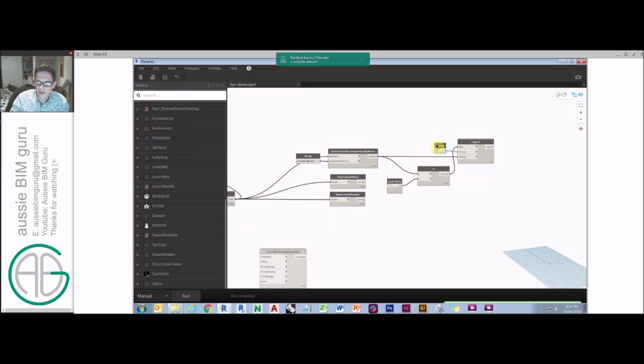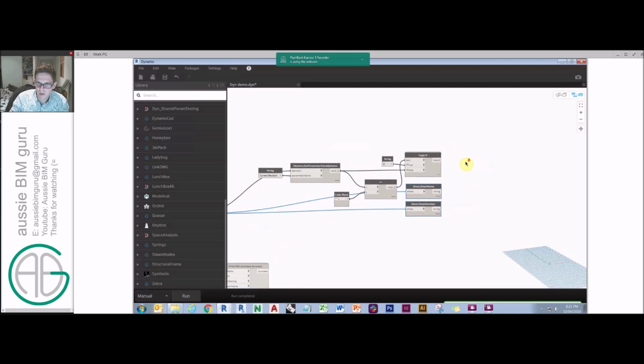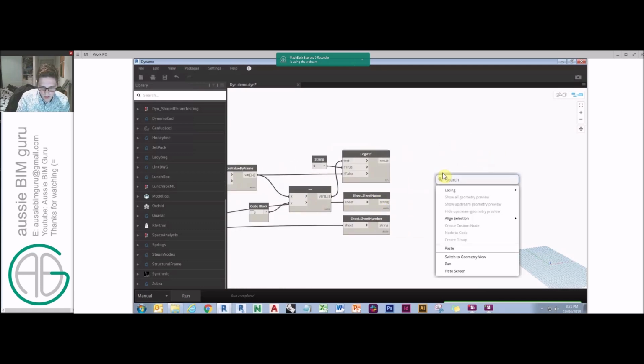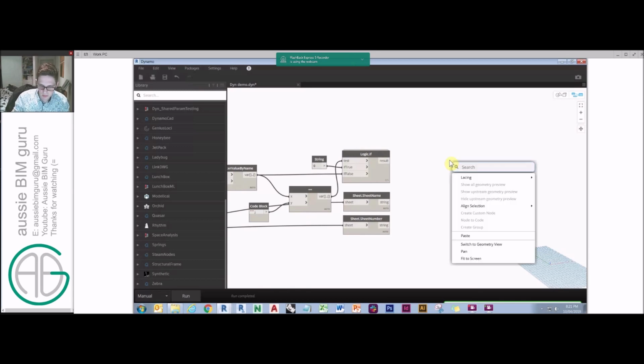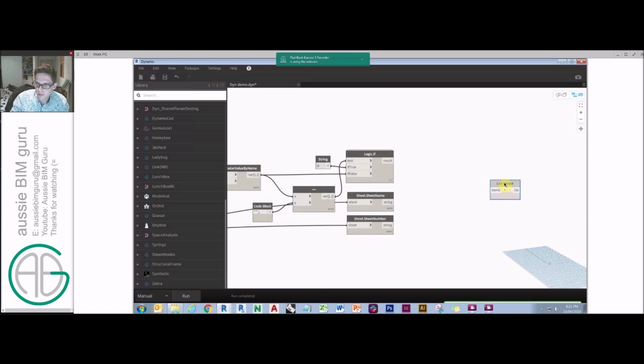So I guess the syntax I'm using is a pretty common one. I've used it in most places that I've worked. So we'll just try and clean that up a little bit. So essentially we've got sheet name, sheet number, and revision. From there, we actually want to put these together. So I'm going to create basically a big list, transpose it, and then concatenate. So I want to basically prepare some lists here.